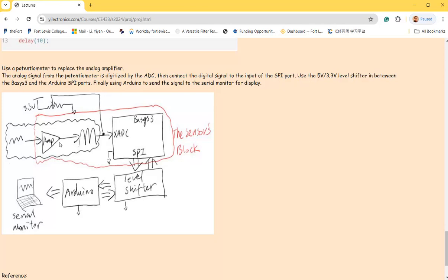But you need to know, as an electrical and computer engineering student, that you need to pre-amplify the analog signal and filter out the offset, the noise, and everything, and bring it into the range of your ADC's range. For our example, it's 0 to 2.5 volts. So the analog voltage, the variation, could be temperature, could be light, could be a lot of things. They have random offset on it.